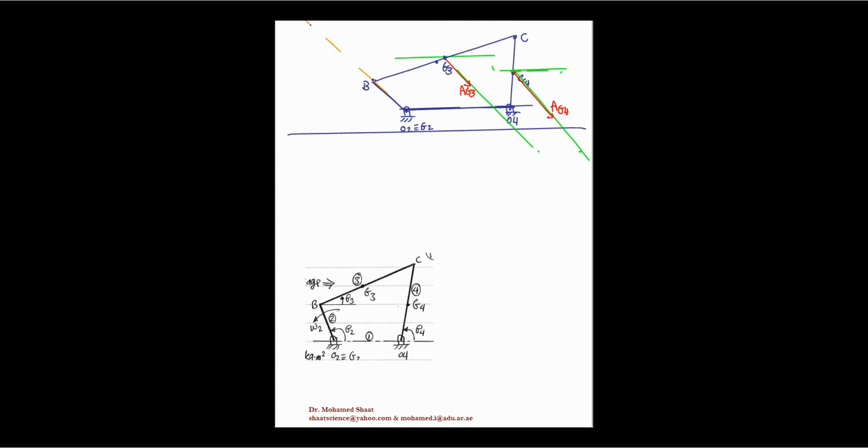Moving to link number 3, we got the inertia force for the link as 47 Newton, but we have no clue about its direction. Its direction automatically should be opposite to the acceleration according to the D'Alembert method that we just explained. So at point G3, you're gonna draw a line that is going opposite to the direction of the acceleration EG3. This is gonna give us the Fi3, which is the inertia force that we just calculated before. Fi3 in this way. Make sense? So this is gonna give us the Fi3 direction.